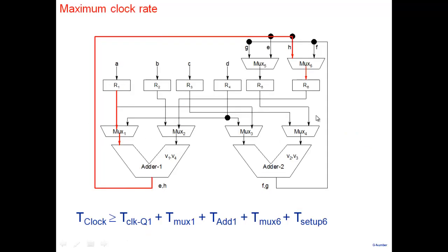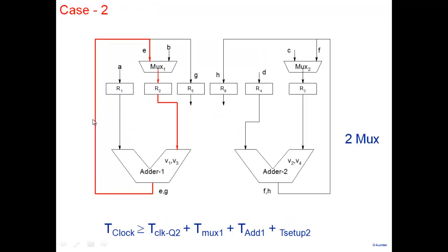Look at the complexity, running wire here, all this. And look at this one here. Very neat breakup of the system. And so I require only 2 muxes here. So note that the complexity, or the simplicity, is even more than simply measuring in terms of mux. Yes, I have 2 muxes compared to 6 muxes earlier. But also note that no wires running back and forth.